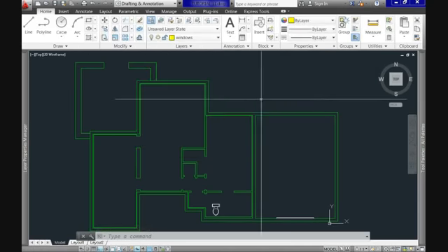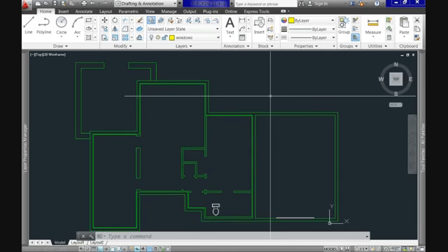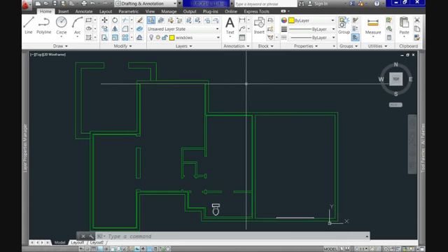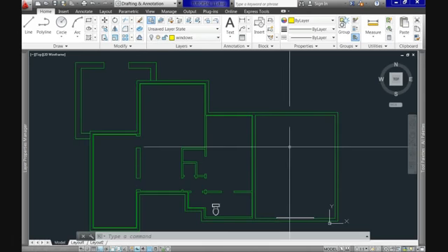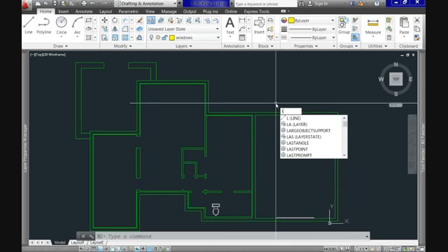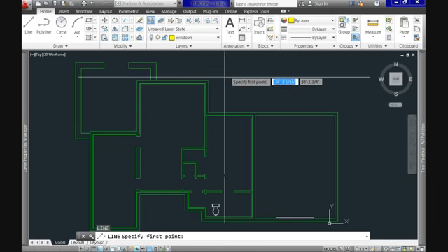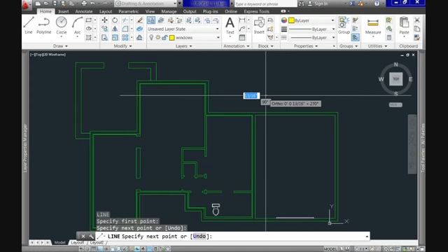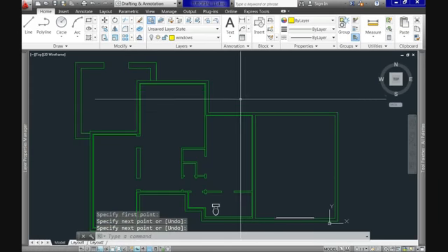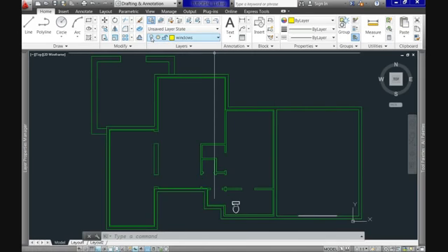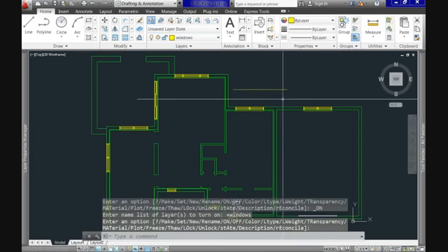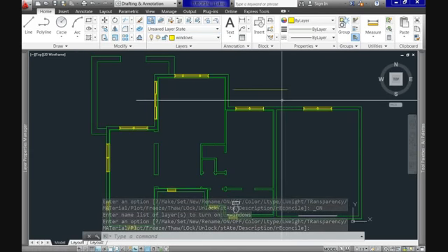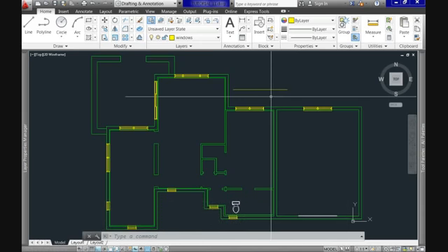An important detail here is that you can turn off the current layer and keep drawing on it. So the detail is that you won't be able to see the results until the layer is turned back on. So for instance, you might think that something is not right because you don't realize that all you're doing will not be seen on the screen immediately. For example, if I do a line in the layer that is off, it will be seen when the layer is back on again, as you see now. So even though the current layer is off, you will be able to draw on it.